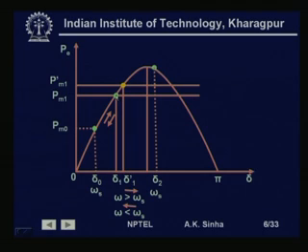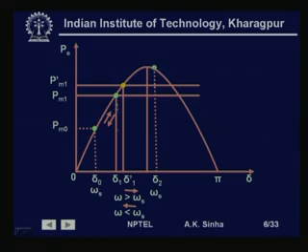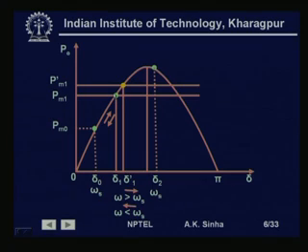Now, when we reach this point, the power angle or the rotor angle of the machine is equal to delta 1, and the electrical output of the machine is going to be equal to Pm1 at this point. So, at delta 1, the electrical output will be the same as the mechanical input to the system. So, now there is no accelerating power available, that is both electrical and mechanical power are equal to each other, and so we would expect the system to start operating at this point.